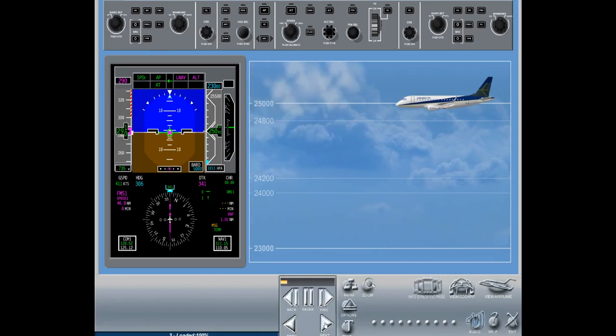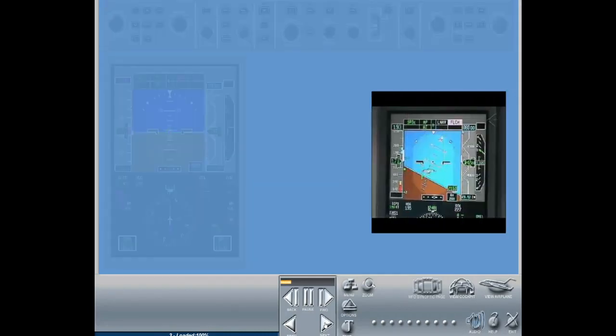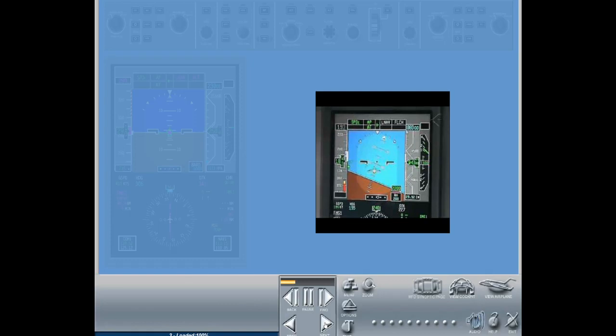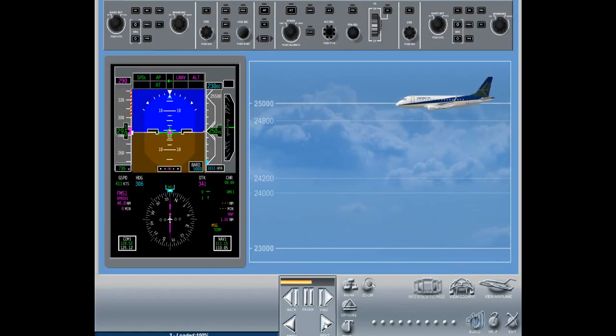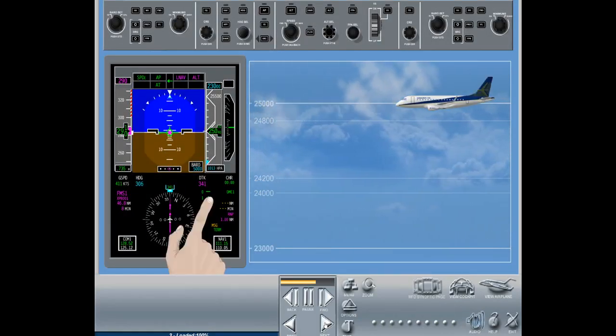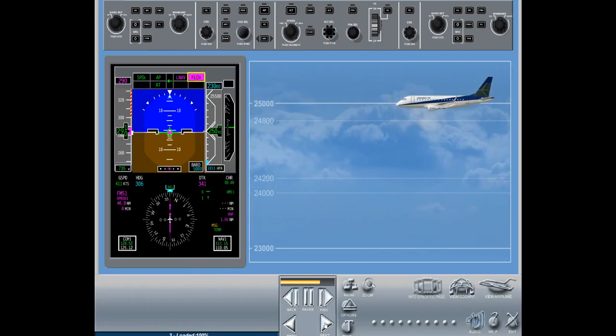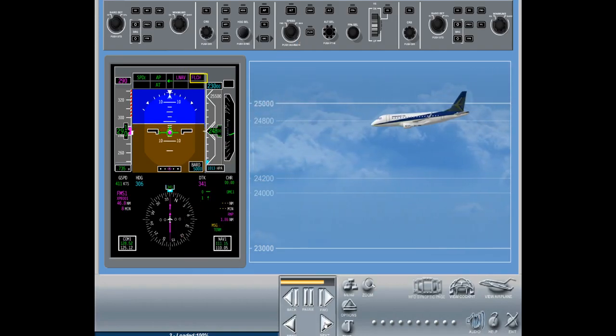VFLCH, VNAV Flight Level Change. In this submode, the AFCS maintains the manual or FMS speed by controlling the airplane's pitch attitude. When in V-alt mode, the V Flight Level Change mode can be selected by pressing the FLCH button on the GP with the Alt selector set to an altitude different from the present airplane's altitude.